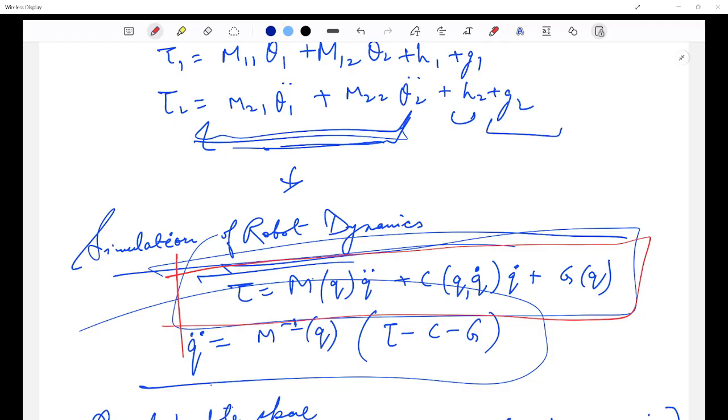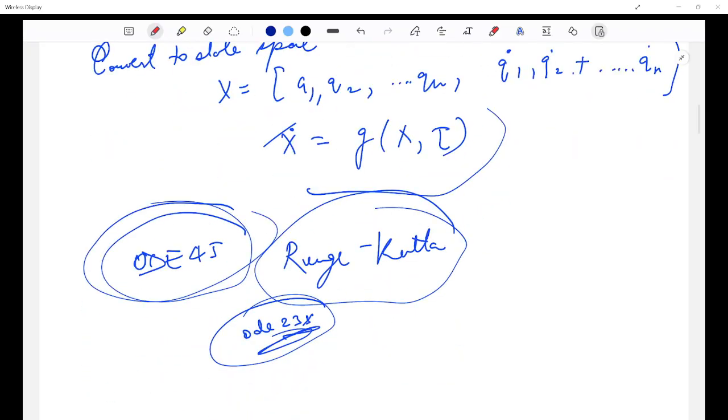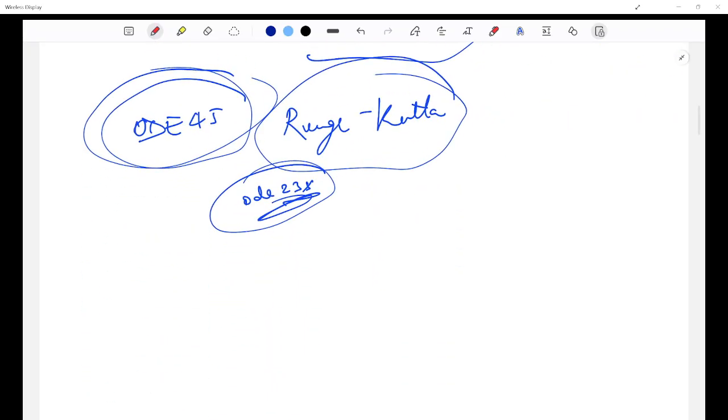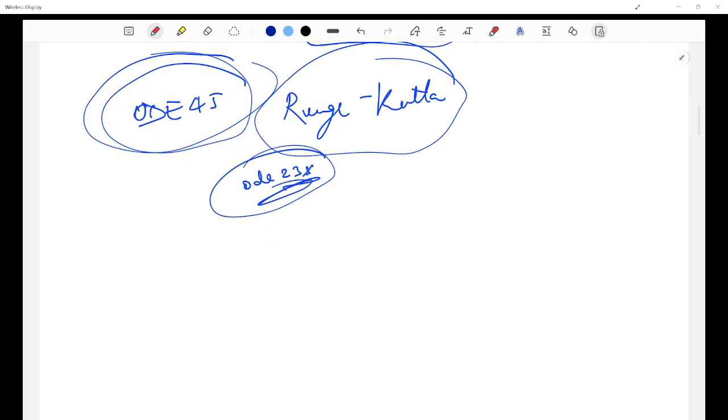The other question is, as we talked about, if there is a torque at some joint, does that torque depend only on that joint? No. In robots, any torque can depend on a combination of joints. For example, links are connected rigid bodies, so motion of one link changes the inertia of the others. For example, in a double pendulum, all the joints do affect each other, and they shouldn't be dealt with independently. What are the Coriolis forces that we talked about, the C matrix?